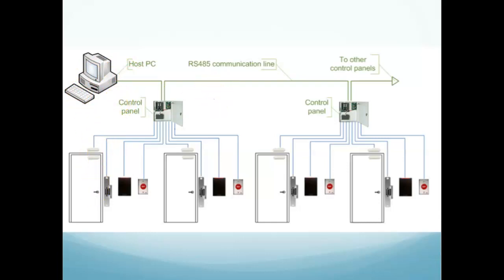That's the basic configuration. It's a door strike or an electric or a mag lock. It's a reader that's presented, a credential presented. Both of them go to the control panel. The control panel makes the decision. It uses the information from the card that's sent up this way. And it says, yes, that's a good read. That person is allowed in, and it sends the information back down here, and that goes click, and the door will open. That's simple. Just make sure that everything goes back to the control panel.